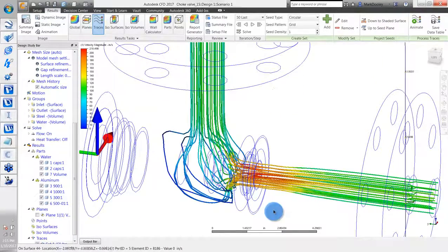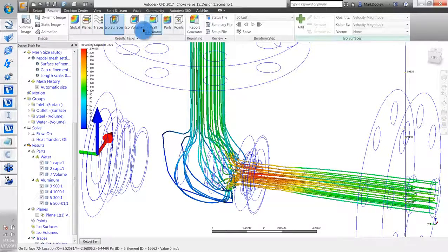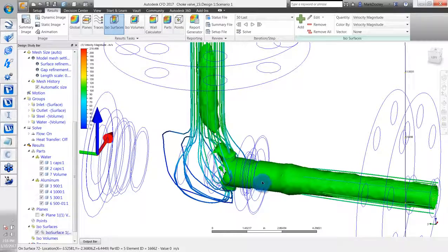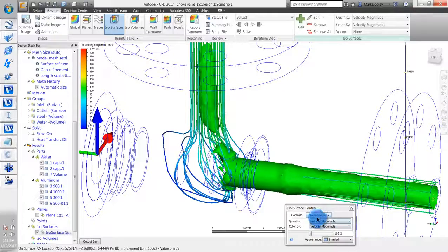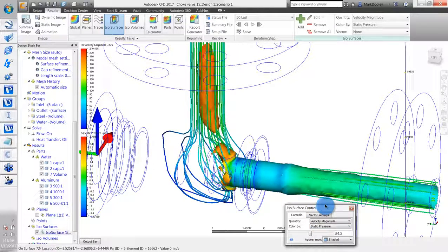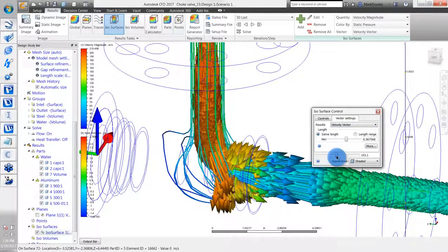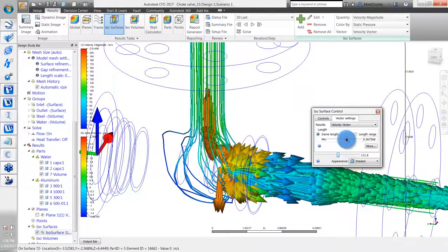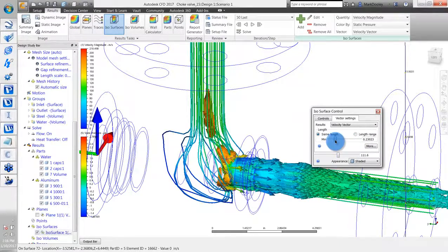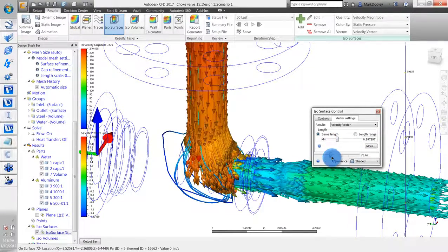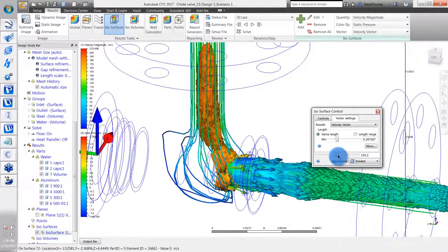The high pressure points, the low pressure points, we've got a graph here as to where we're at, where we're going. We can create ISO surfaces if we want to create one of those, ISO meaning singular surface there, and we can change this to our pressure if we'd like to see our pressure, and we can change that. We can go to the settings here and look at our results, and again we can change the bar here a little bit, slide this back, control the arrow size so that we can tell the story of where our pressure is coming and where it's going.